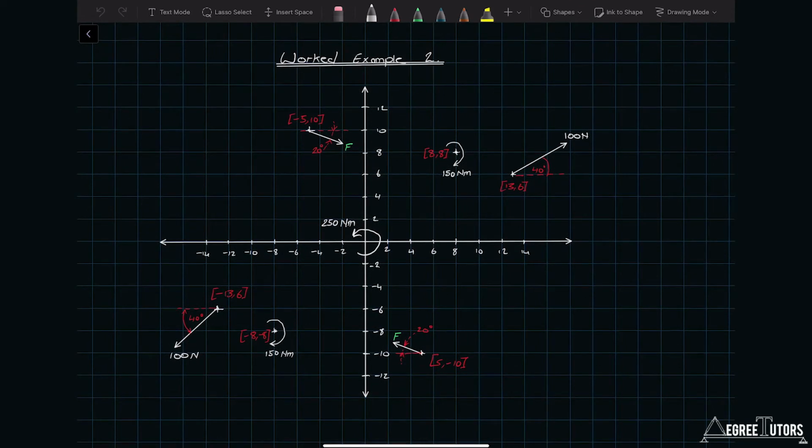So we've got a couple F. Okay, so we've got the force F, this one here and this one here. And so those are two forces. F and F indicates they have equal magnitude. They're parallel lines of action indicated by the angles of orientation here and here, and they point in opposite directions, so they form a couple.